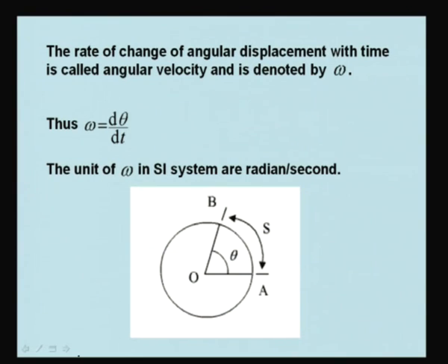Since all the bodies moving in a particular plane will have the velocity either in plus k direction or in minus k direction, angular velocity will be like that. Therefore, we generally omit k and instead indicate the angular velocity by just either a positive number or a negative number. So, we can manage it by just algebraic addition and subtraction.